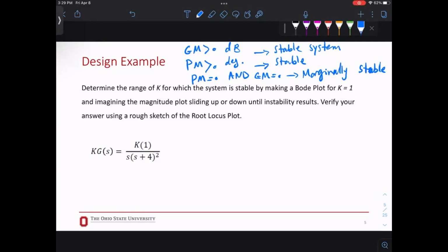You can even find the poles from the Bode plot, because pole S is j omega. If you have the omega, you know where the pole is, right? You could even say if it is a conjugate pair or just one, if it has a pole at the origin or not. You can interpret all that information from the Bode plot, all right? At least the hope is that you'll be able to go between all three domains.